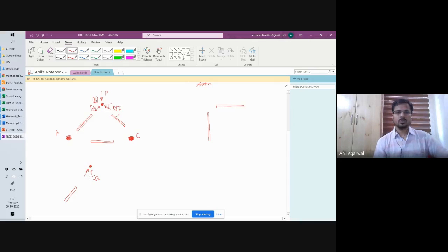So this action of P by root 2 was acting on B, but it was being applied by the member AB on joint B. In this direction. So the reaction has to be equal and opposite on member AB. And that will be P by root 2. That is Newton's third law. This is not coming from first law or second law.